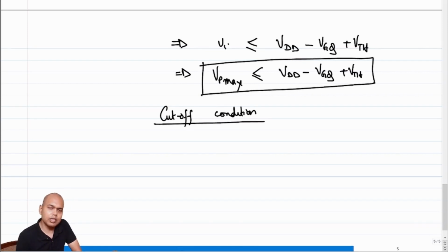And also we saw that the condition for small signal approximations to hold is that the incremental VGS has to be much less than the overdrive of the transistor, right? So since that has to hold, we cannot anyway shut the overdrive to 0, right? So throughout the course we will use the condition of quiescent plus incremental, right?